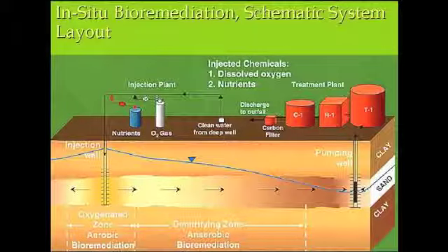In situ bioremediation methods treat the contaminated material on site. The methods include bioventing, biostimulation, air sparging, natural attenuation, land farming, phytoremediation, and bioaugmentation. The target contaminants are usually fuel, non-halogenated volatile organic compounds, semi-volatile organic compounds, pesticides, or herbicides. Most of the methods are not very effective with halogenated contaminants if the compound is tightly bound to soil particles or if there are high concentrations of inorganic salts, heavy metals, or organic compounds.